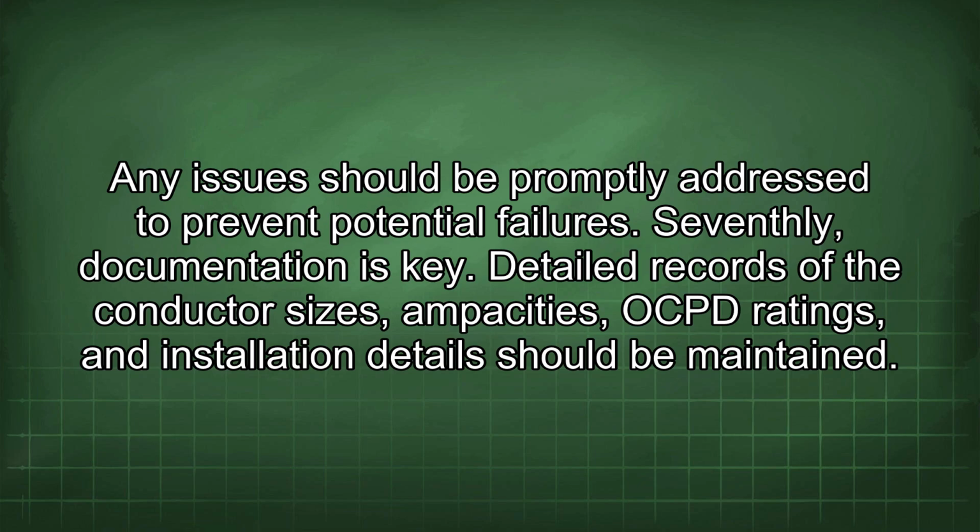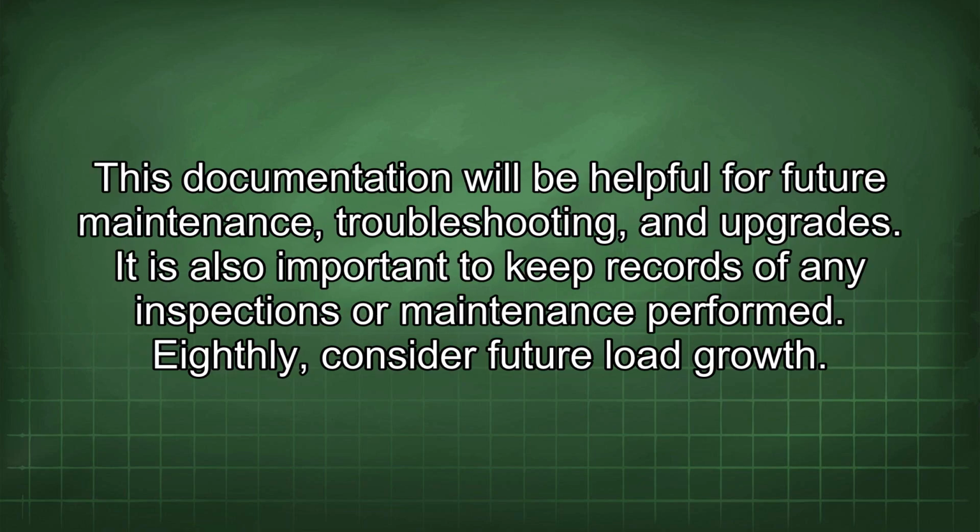Seventhly, documentation is key. Detailed records of the conductor sizes, ampacities, OCPD ratings, and installation details should be maintained. This documentation will be helpful for future maintenance, troubleshooting, and upgrades. It is also important to keep records of any inspections or maintenance performed.